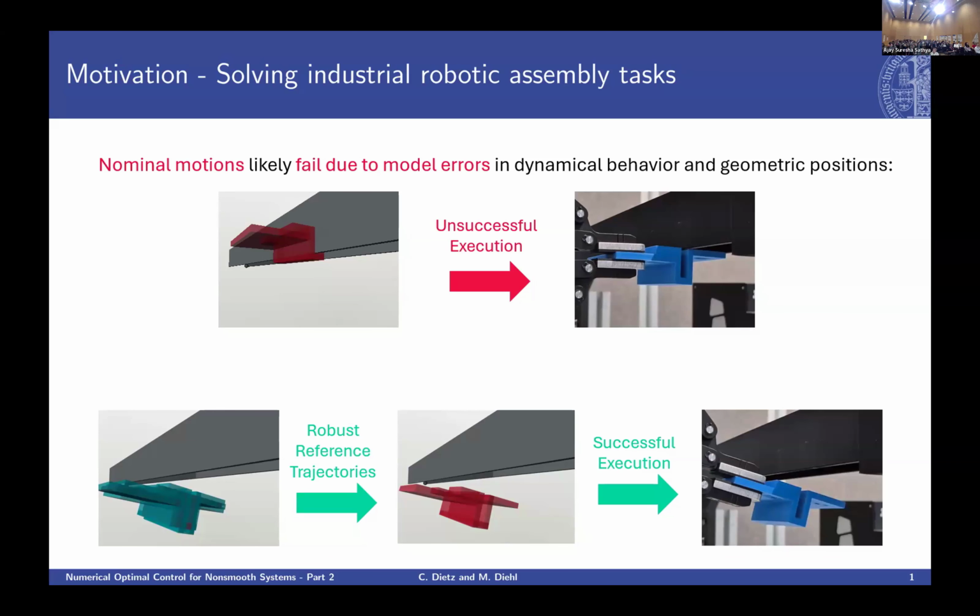So we want to obtain a robust solution for our problem, and we do it by considering multiple instances of the object. Each instance tracks a reference trajectory by an impedance law at a constant positional offset. If you would not have the constant positional offset, all instances of the object would collapse immediately to the reference through the impedance law.